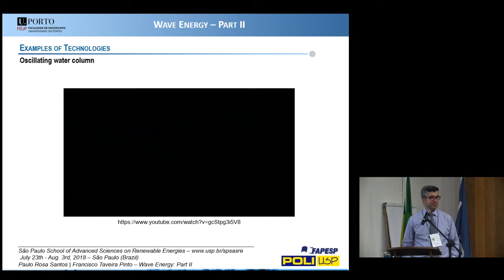Just a quick question. I was wondering, the 400 kilowatt power, it's actually always changing, right? Yeah. So depending on, there is a rated power, but usually the mean harnessed power is much smaller than that value. Okay. So the system was prepared for that maximum power, but in average terms, maybe 8 times less or so, because the wave characteristics change a lot, and the power of the wave depends on the square of the wave height. Okay.